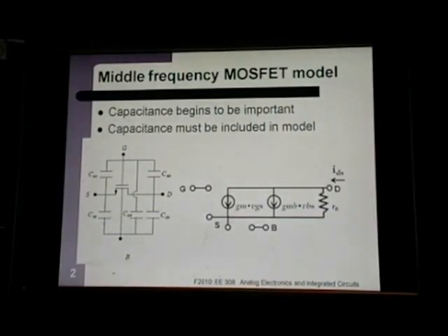To remind you, the way we found our poles so far, since we have really only talked about poles, is that we talked about transistors and how when you simplify them down, what they end up looking like is a current source into a resistor and a capacitor in parallel, and a resistor and a capacitor in parallel with a current source into them looks like a low-pass filter.